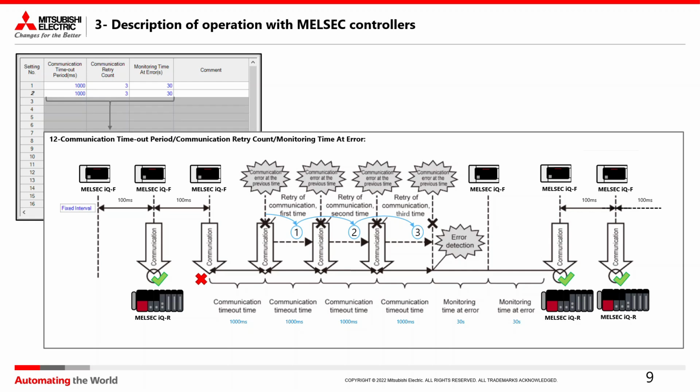From this moment, the function enters a monitoring state where the error code is updated after the set time has elapsed. In this monitoring phase, communication is automatically reestablished when the problem is resolved. In the on-request mode of setting, the monitoring phase is not performed and the function ends the execution after the end of the communication retry count.